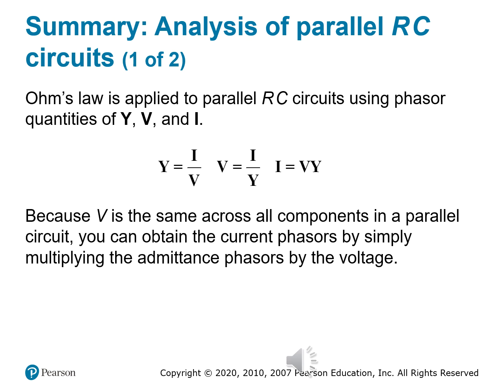So here's where the fun begins. We switch from using impedance, denoted by Z, to admittance, denoted by Y. And the equations, we can break them down into admittance is the reciprocal of impedance, so Y is equal to 1 over Z. We can rearrange Ohm's law for admittance to give us I is equal to V times Y, right? So if you know the voltage across the circuit and you know the admittance of a branch, you just multiply to find the current phasor. And that's it. It's that easy. Nothing changes with Ohm's law. These relationships stay exactly the same. The math becomes a little more fun.